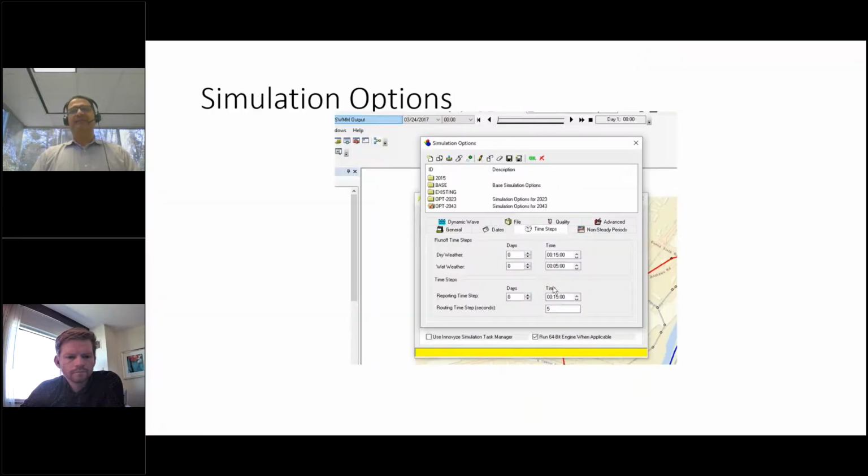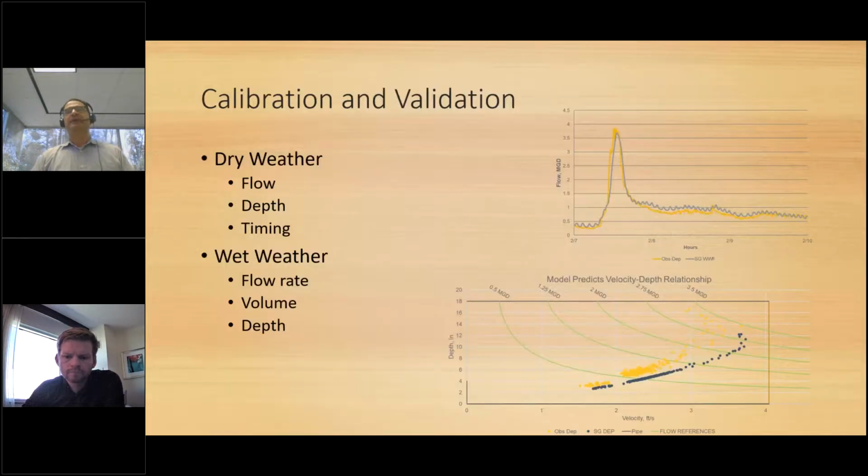And that can help with controlling the simulation. I sometimes run it with a coarser time step until I feel comfortable that I reached the solution or the stability or the continuity error that I desire, and then I would switch to a finer time step and get higher resolution. For the calibration and validation, we look at